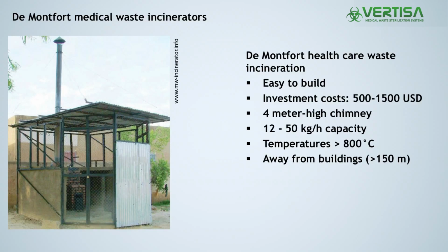Then there is also incineration. One simple incineration system is the De Montfort incinerator, as a cheap but effective incinerator which can be built in almost any developing countries. It reaches the criteria of a temperature above 800 degrees with a residence time of over 1 second.